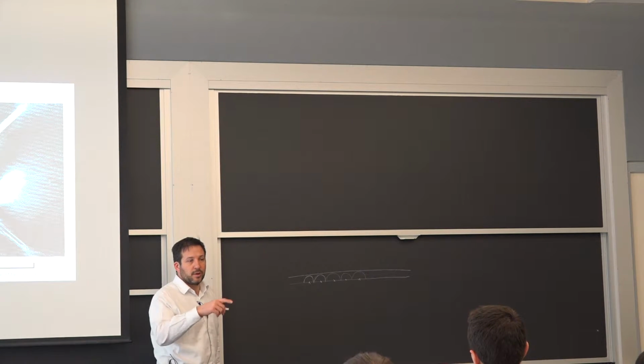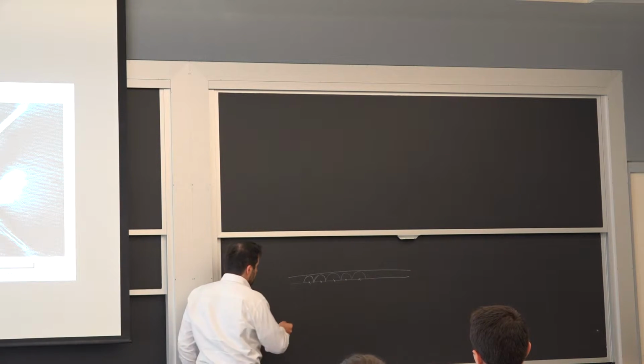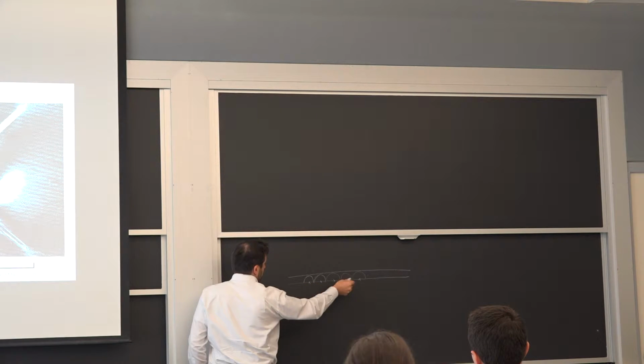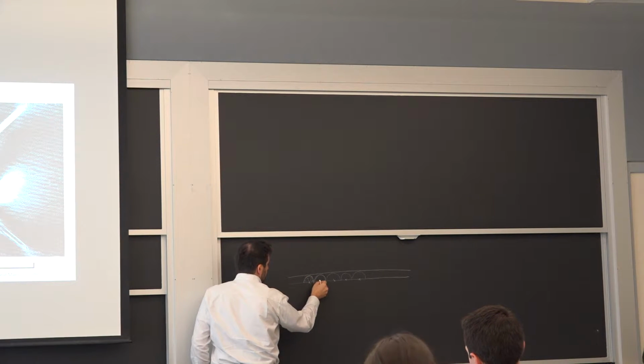So what we learned from that is there were a lot of initiation sites. There wasn't just one big particle that was causing the problem here. There were essentially a lot of locations where the crack started, and a good amount of time was spent growing that crack slowly.